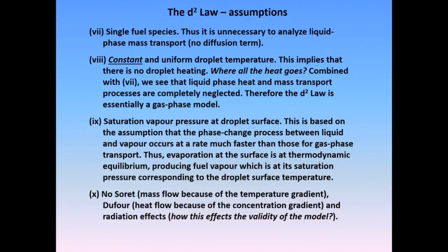Some of the additional assumptions are that you have to assume a single fuel species, or whatever species you are assuming, and a constant and uniform droplet surface temperature. That means there is no spatial variation of the droplet surface temperature, and no temporal variation of the droplet surface temperature as well. And it is basically a gas phase model, we will not do anything to the liquid phase.